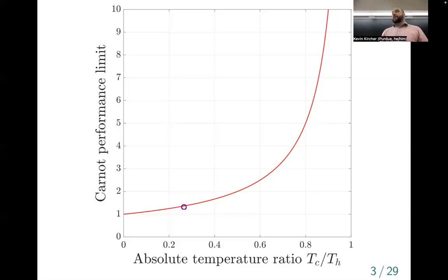If you want a quick and dirty approximation of the actual COP of a real machine, you could get a sense for what percentage of the Carnot COP your real equipment can deliver as a function of the boundary temperatures. Then you get a curve like this, but shifted downward on the y-axis. A real practical machine that you can build or buy might only get maybe 20 to 30% of the Carnot limit. So it might have the same sort of shape, but shifted way down.